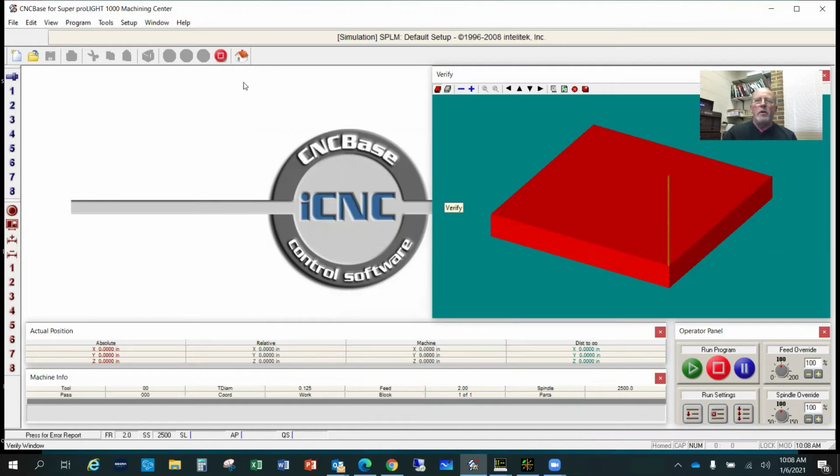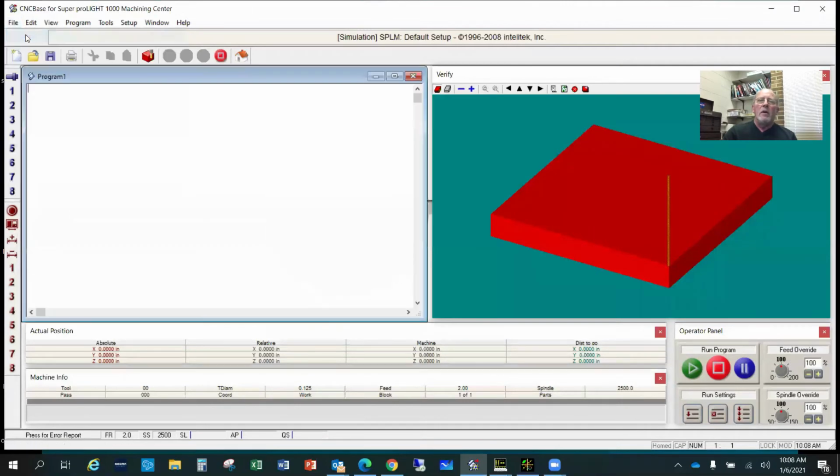And what we're doing here is we're learning M and G code. It will be the basic M and G code at the beginning. I'll allow you to use notes, of course, but we have simulations. So if I hit File and New, and then turn on my caps and start giving it different codes, a G90, for example, would be absolute programming. A G70 would be inch programming. And I would say an M06 T5 would be for a tool. M06 is a tool change.